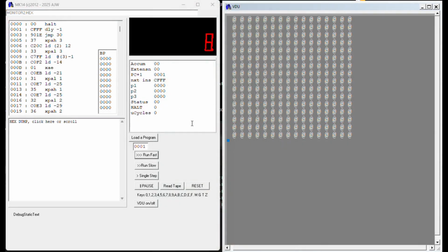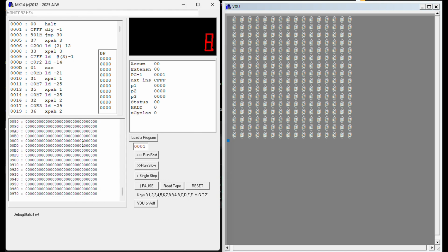Again with the PC application, I'm going to explain a little bit about the addressing system on the MK14. Some address spaces are duplicates of each other. I call them mirrors. Now if I click on this space here, you can see the contents of the entire memory all the way up to FFFF, which is the maximum the MK14 address space goes to, all the way from 0. The first two 256 blocks take up these spaces here in ROM, which is within this memory space,